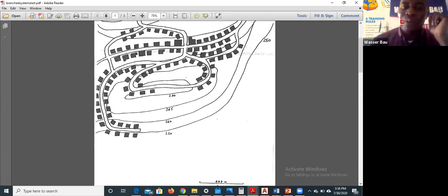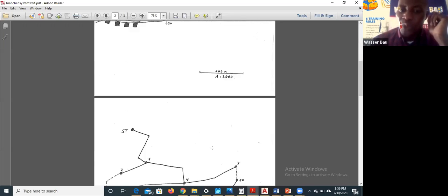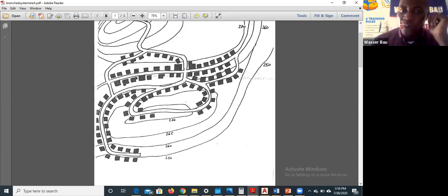If you look at this diagram, there's no house between node 4 and node 8. Node 4 is here and node 8 here. This other house you're looking at is along this street. So the base demand in node 8 is also 0, but the value at node 7 is 1.2, and at node 9 about 0.46. If you add those together, you'll get about 1.7.